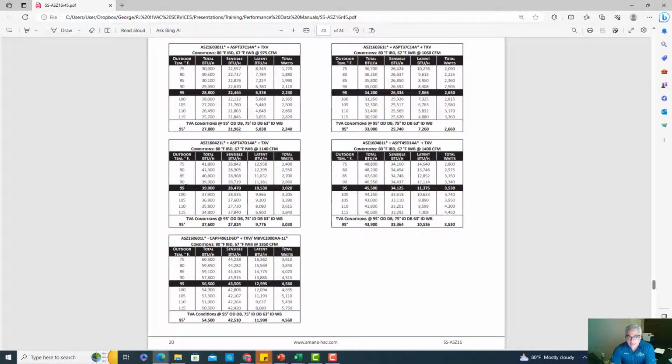Now, have we had days where we got a little hotter? Yes, we do. But look what happens also. Your BTU capacity reduces. The ability for it to cool reduces. And the usage of the wattage increases. Now, when we're not at peak conditions, which we're not always at, we're at peak conditions maybe 1% of the time in total, especially when you saw the average on the year, we're at 69 degrees on the year, which is lower than the 75 target temperature. But if we were to go with this average, let's go with the lowest here because our average on the year is lower than 75.